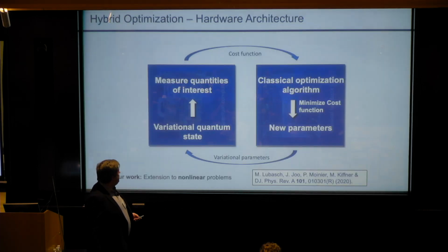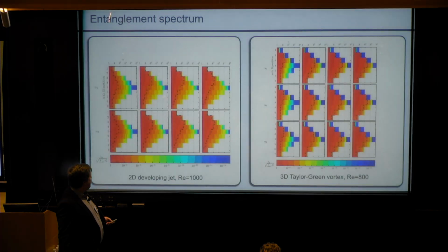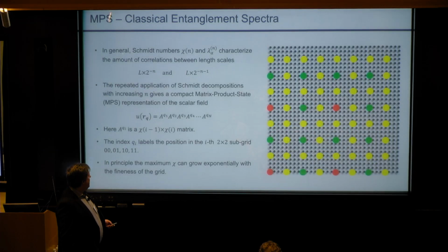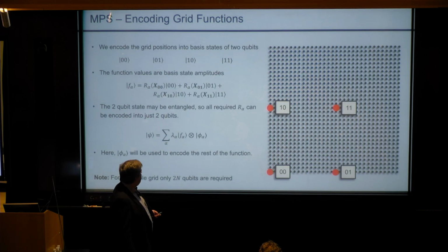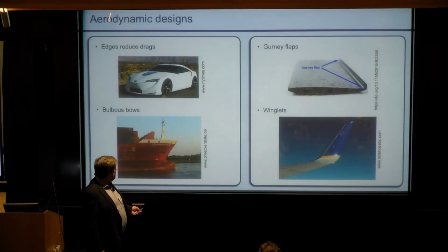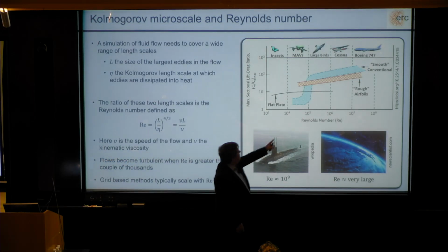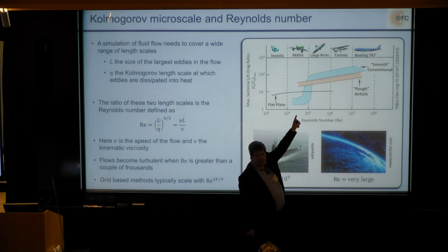You did see there were some examples on these airfoil problems where you have a certain transition in the airfoil quality at a Reynolds number of about 10 to the 5 or so. See here, at around 10 to the 5, for instance, conventional airfoils suddenly have a huge change in what they do.